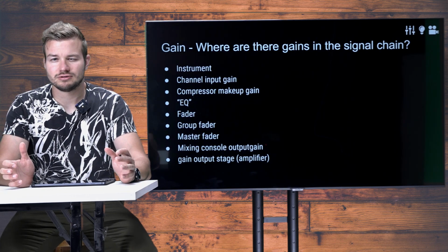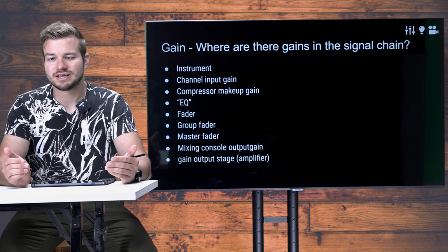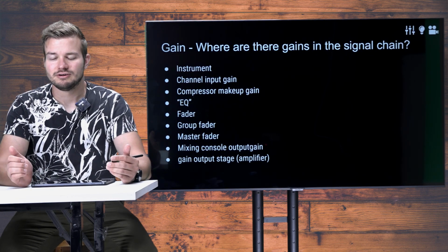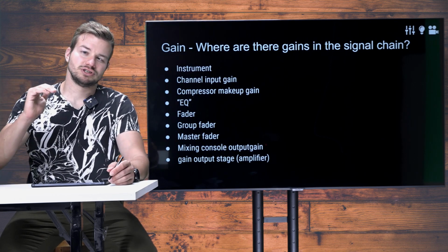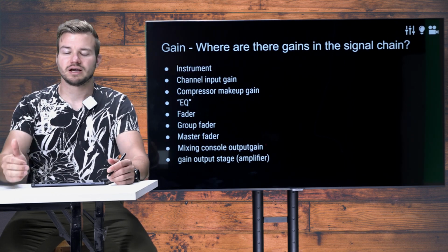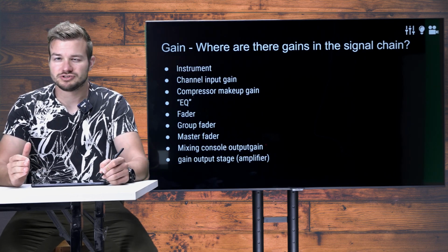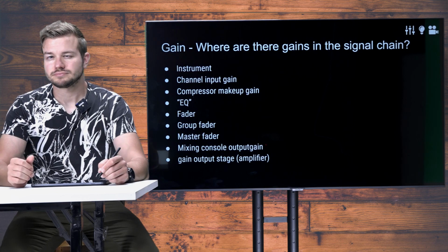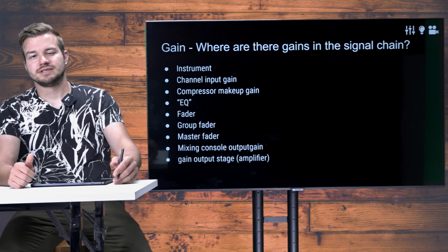Our final goal is to use the signal we get and always have it in a range we can work with well. What does that mean? The signal should not be too high and it should not be too low. I'm always talking about the amplitude here. If it is too high, it will overdrive, it will crush, and it will basically be destroyed, so it does not sound good anymore.